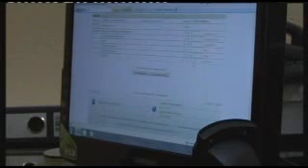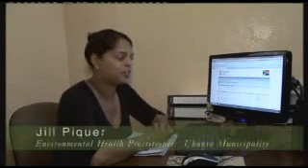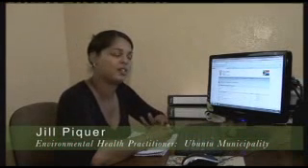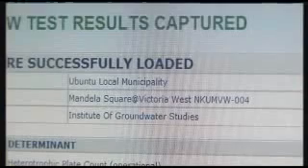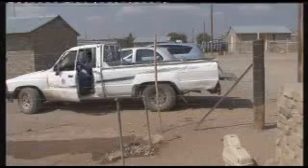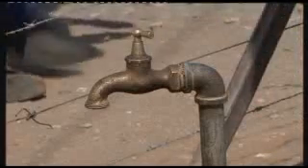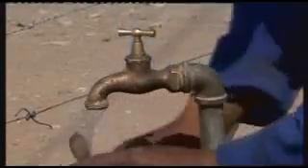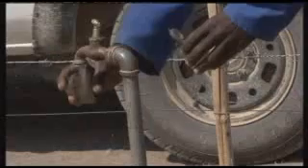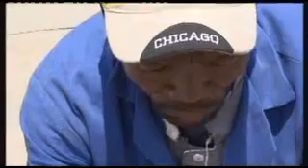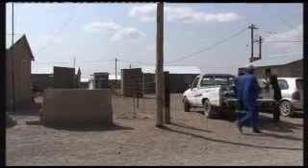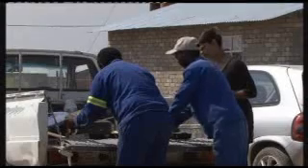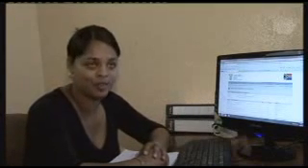The system that we are using in Victoria West is the Blue Drop system from the Department of Water Affairs. This is to help them get the information quicker. So we do our operational testing twice a week and our bacteriological testing once a month. Those test results are captured on the system and directly processed to their system. In total, we have 4 sampling points, including the reservoir, so it's the point of use as well as the source. We need to monitor the water at every sample point every month. If we don't do that, it's a not certified audit. The DWAF then get the information and check the criteria, and if it's certified, we get a Blue Drop status for our water quality.